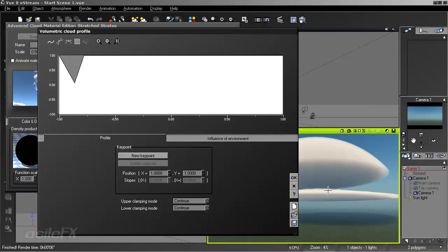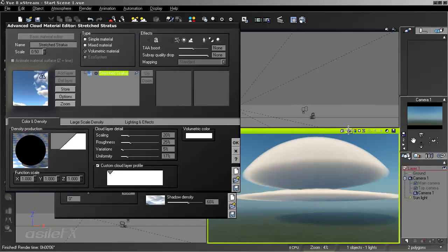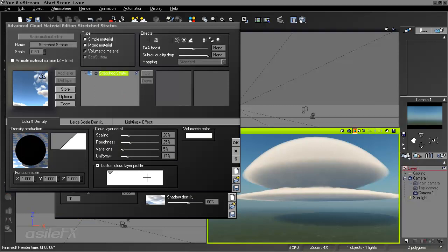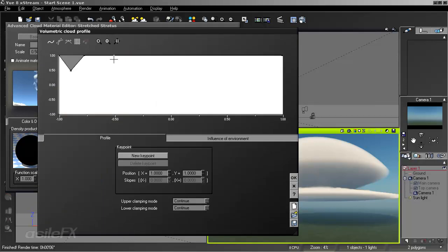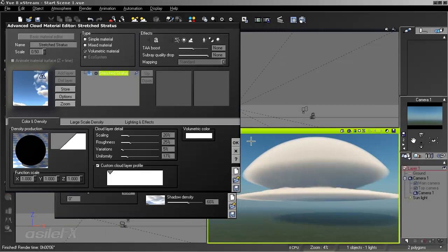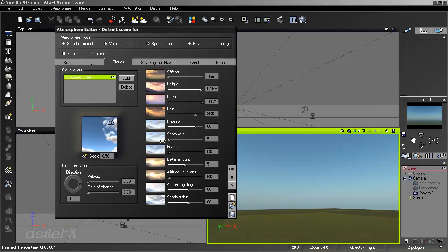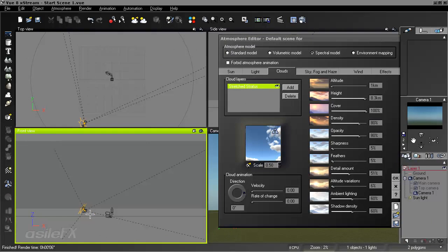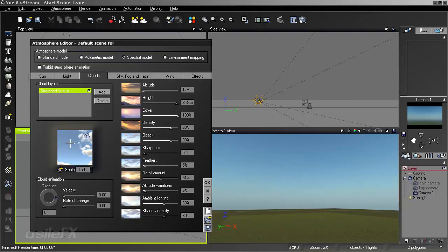And what would happen is if we had a high enough roughness setting, we're going to see more roughness in the area. So if we keep it around 0.5, we're just going to have a smaller dip. So very tiny amounts and changes within the profile can severely impact this. You can also see the range too. We're basically falling between -1 and -0.5 for the cloud existing within the total height amount. So it's only a really small amount showing within that total volume. If we take a look in the front view from the side, it's only really raising up a very small amount compared to the total height of the layer.